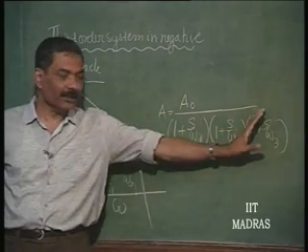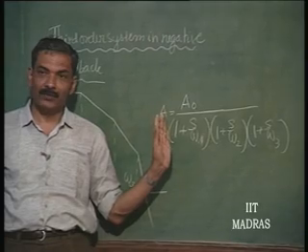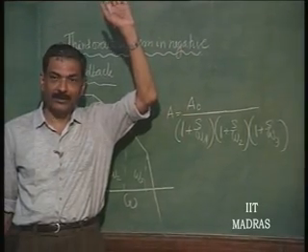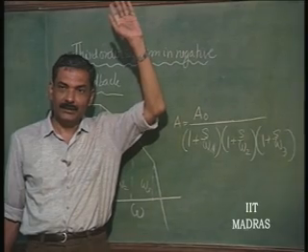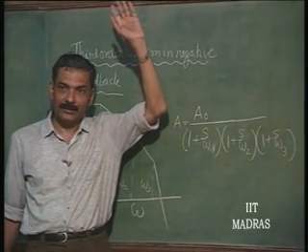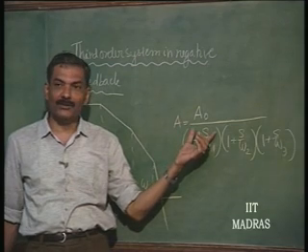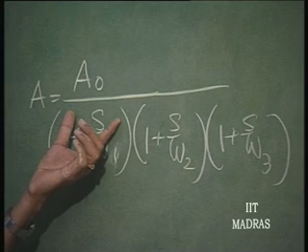When it is second order, the phase shift of A can go from 0 to 180 degrees, that also at infinity frequency. So, there is no finite frequency at which it can become 180 degrees. But by the time frequency goes to infinity, the gain itself falls to less than 1, it goes to 0. So, there is no harm.